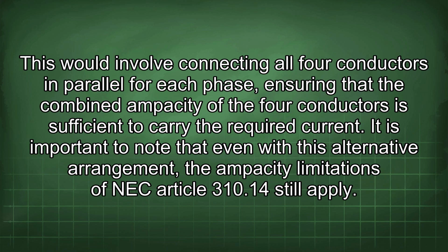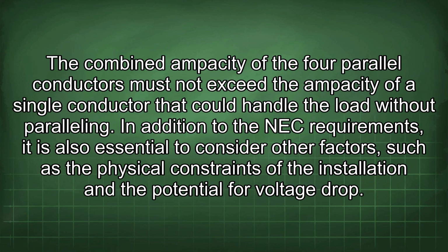It is important to note that even with this alternative arrangement, the ampacity limitations of NEC Article 310.14 still apply. The combined ampacity of the 4 parallel conductors must not exceed the ampacity of a single conductor that could handle the load without paralleling. In addition to the NEC requirements, it is also essential to consider other factors such as the physical constraints of the installation and the potential for voltage drop.